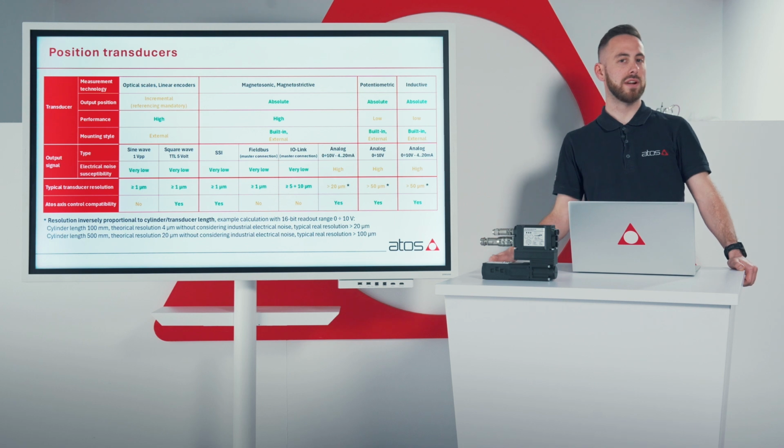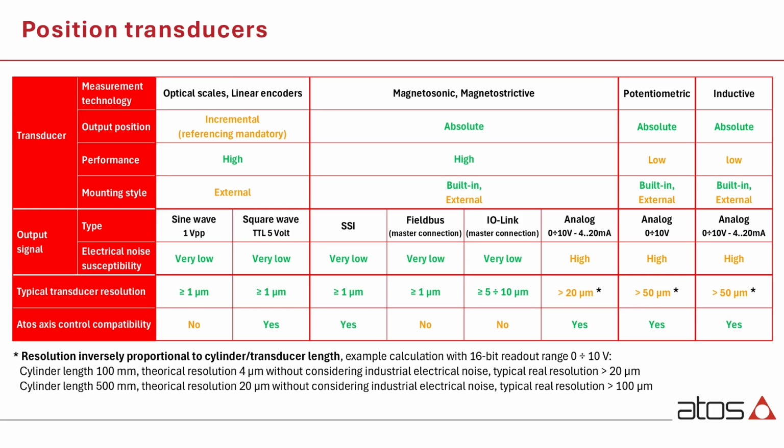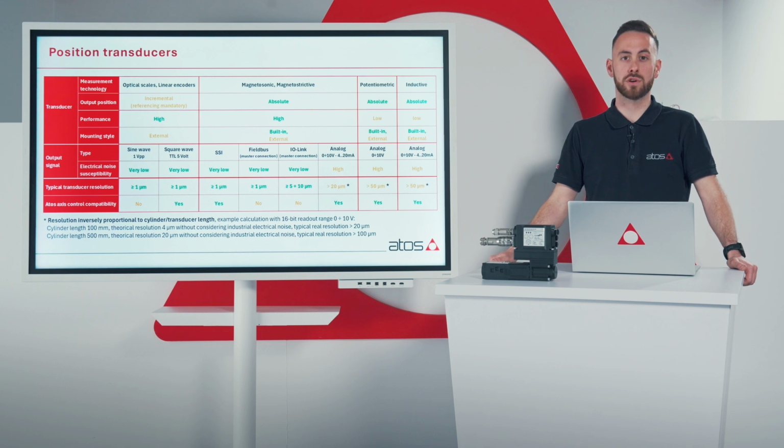There are also several technologies to convert the physical quantity into the electrical signal. The most common and widely used are magnetostrictive and optical scales. This last technology is not really recommended in industrial application, since it typically requires a specific zeroing procedure at every machine startup, and normally is not available for built-in solution. Potentiometer and inductive sensor are not recommended for a high-performance closed-loop system, as the Atos one.